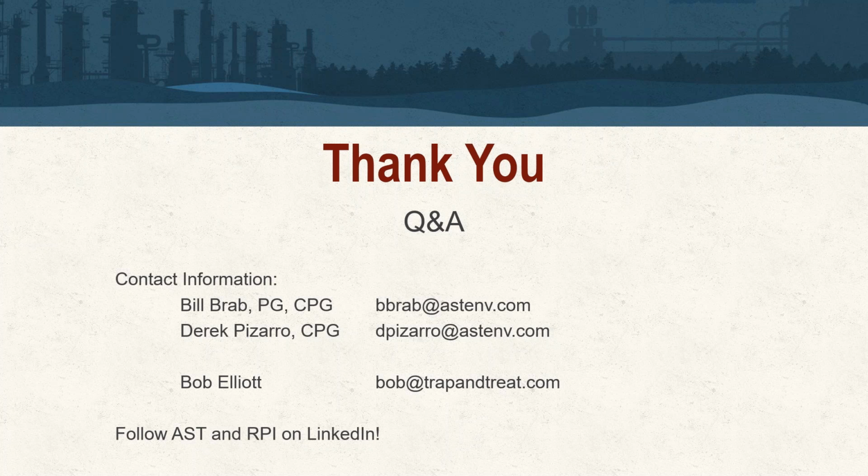Coincidentally, we have a great presentation next week that will address weathered units, less competent formations, transitional zones at the bedrock interface. Our colleague Mike Mazzarese is putting that on. You can register at the Trap and Treat website, trapandtreat.com. But real quick, the systems we discussed here today and last week, we're not going to use most of that equipment, or in some cases, any of it. When we get a weathered unit, we're going to use something we call pre-drill methodology, and that involves using augers or sonic rigs to reach the top of competent bedrock, stop at that interval, and then complete that borehole with hydrated bentonite pellets or chips.